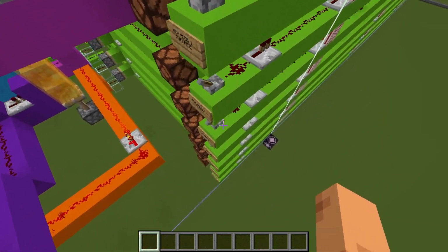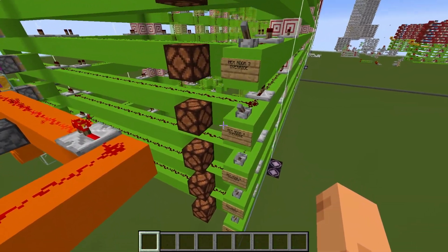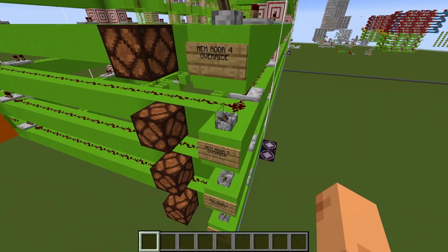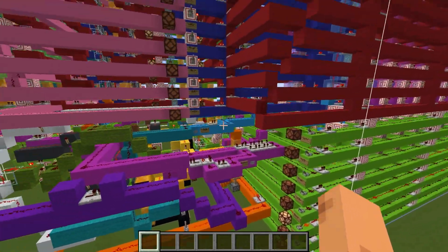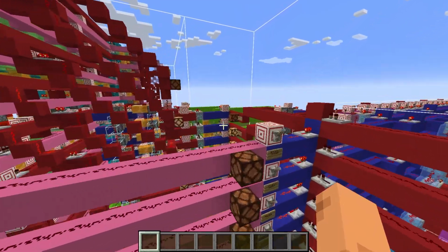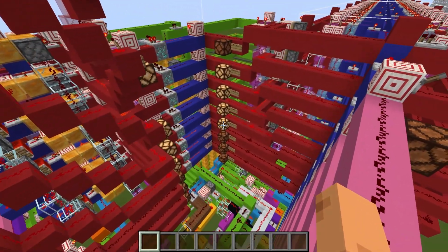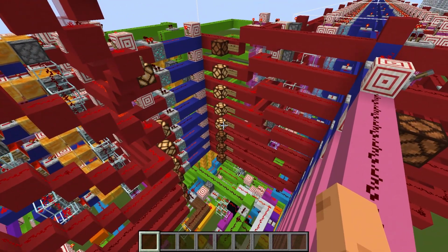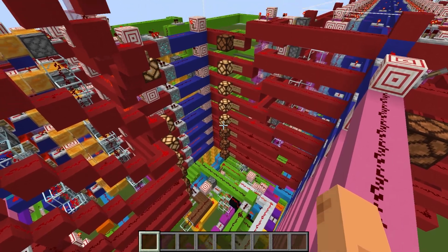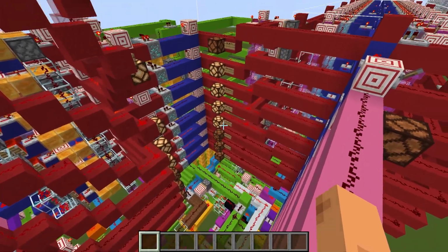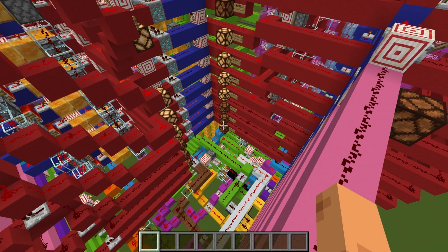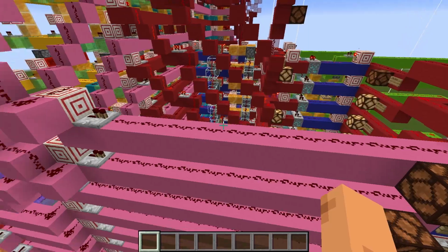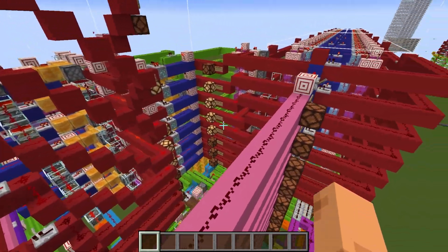So 32 would be this, yeah, bit 5 address enabled. Let's see what value we have at address 32. We have, well, hexadecimal 78. Hexadecimal 78 is value 120. So we got our expected result of factorial 5.